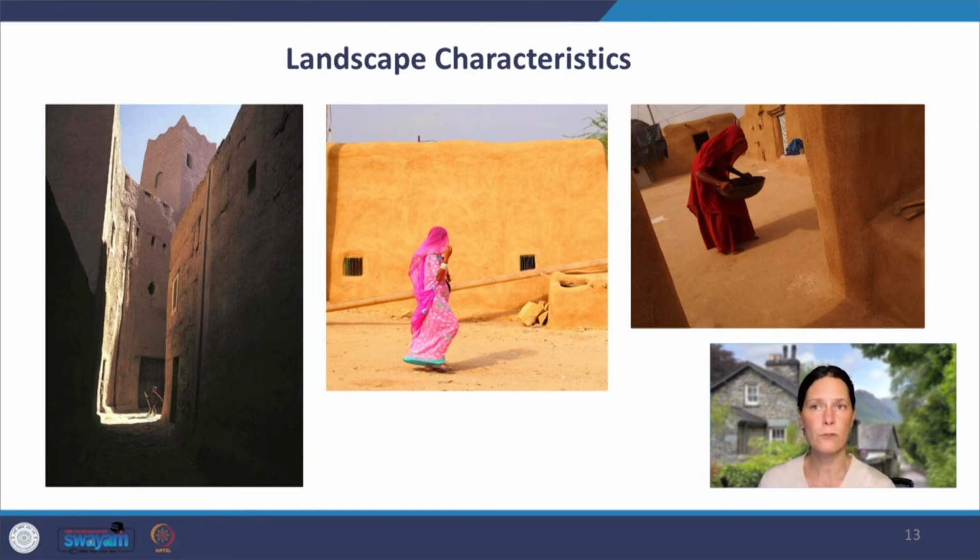The walled, roofless space is rarely as hot at midday or as cold at sunrise, but it's also a response, again, to privacy needs, providing the center of domestic activity, a combination of privacy and outdoor space where women can carry out their needed tasks in comfort. The majority of courtyard floors utilize some combination of compacted earth, porous brick, or unglazed tile. These materials have high heat capacity and they store water, which helps with cooling during evaporation.